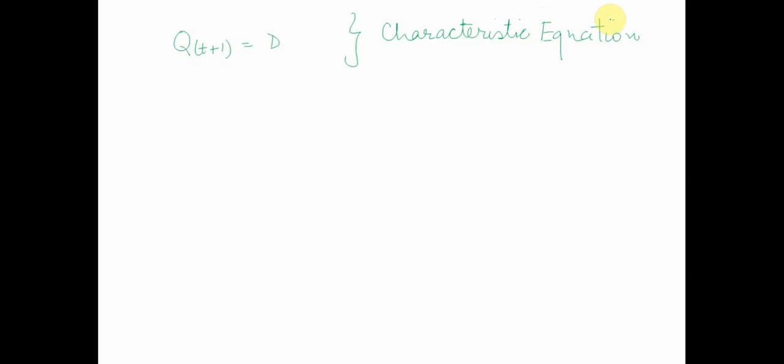Now, similar to the D flip-flop, two more flip-flops are available, called T flip-flops and JK flip-flops. Just to briefly mention these two, we already spoke about the D flip-flop, where we have output Q, Q bar, input D, and C. The characteristic equation of the D flip-flop is next state equal to D.